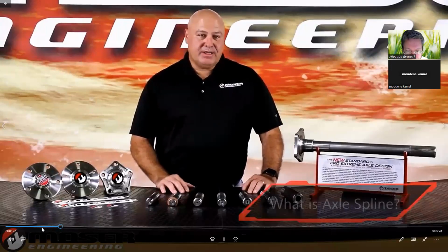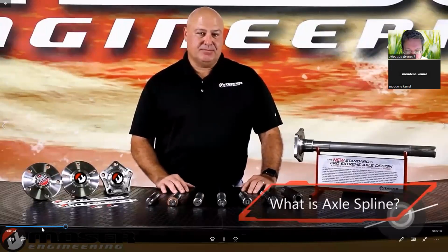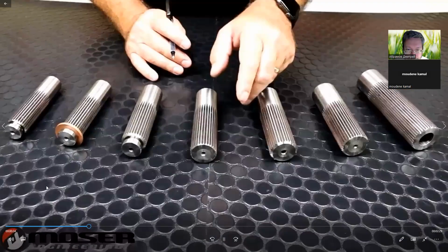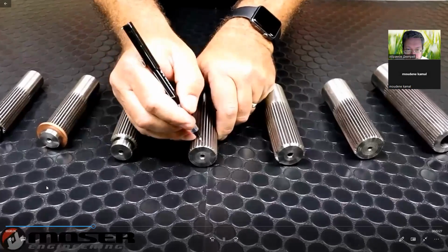Mosier Minute. Today we're going to talk about axle spline. One of the most frequent calls we get is, what is an axle spline, or how do I measure an axle spline? Well, the axle spline is the peaks and valleys on the end of an axle that slides into the differential or spool. When we ask you what your spline count is, what we want you to do is count the number of peaks